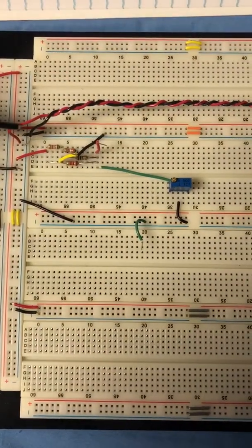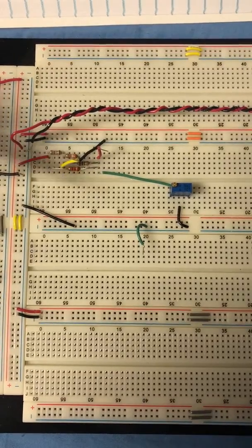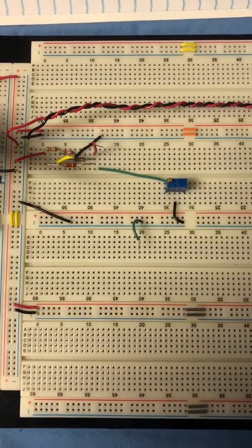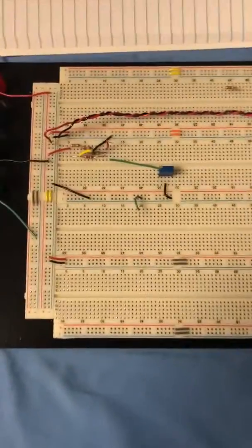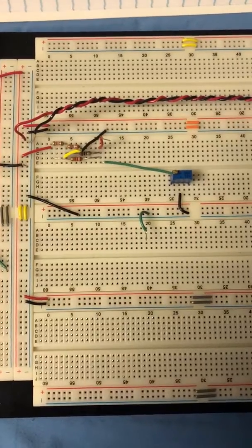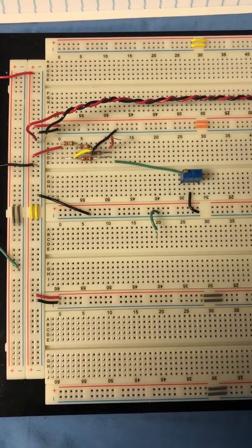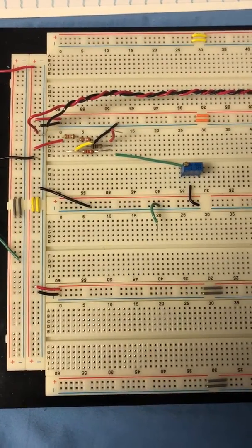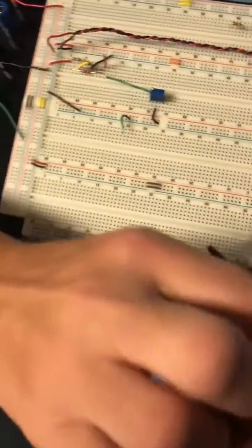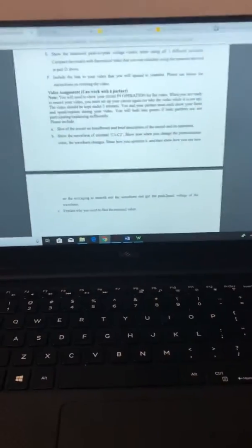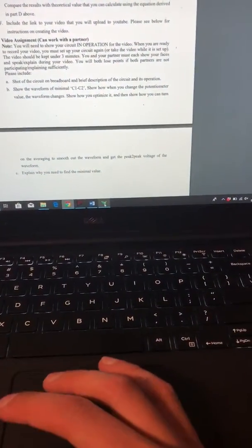So we have the circuit plugged into the function generator. We'll hook up the probes and use the program Waveforms to find the correct potentiometer resistance that will create a 0 voltage across resistor 3, which will help us solve different elements of the circuit. So I will set up the probes while Brian goes onto the Waveforms and gets things set up.